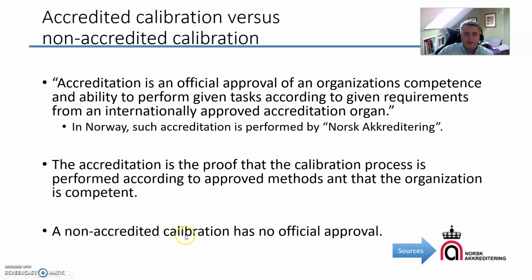A non-accredited calibration has no official approval, so I can, of course, calibrate my instrument in the lab, but if I want a certificate of my instrument, I need to go via the chain of accreditation.